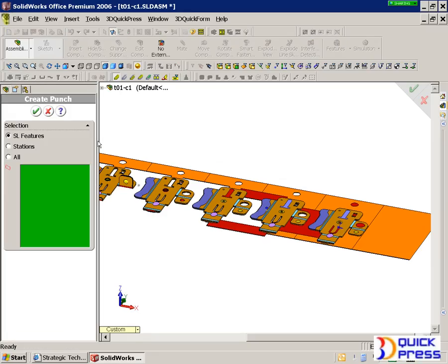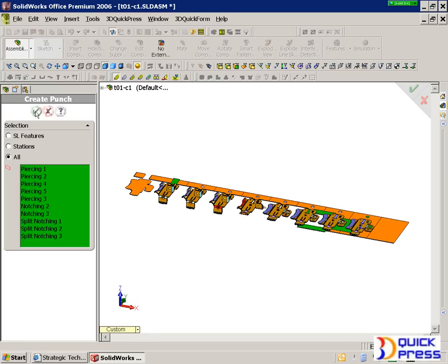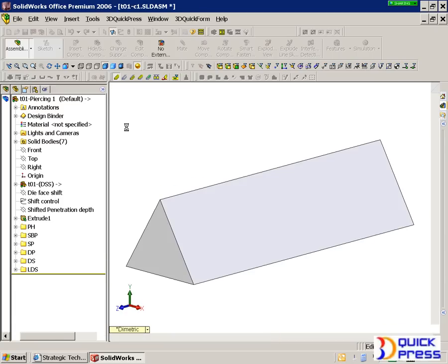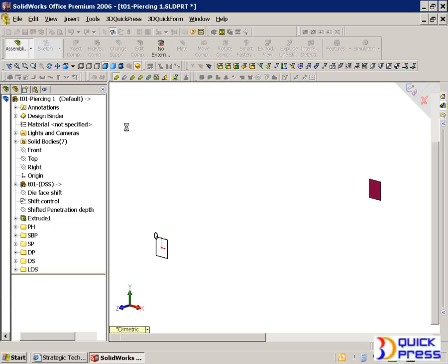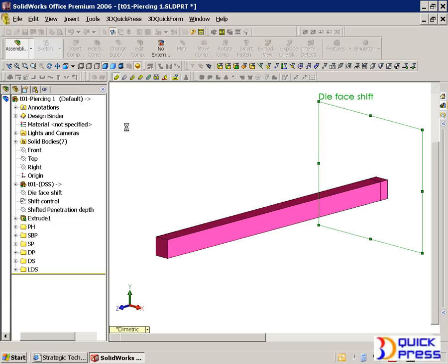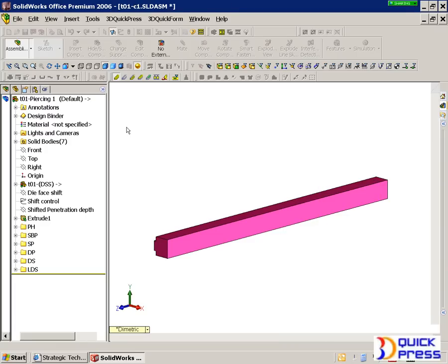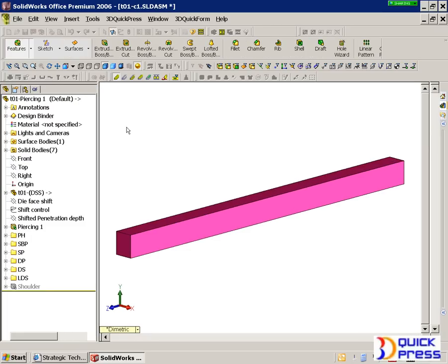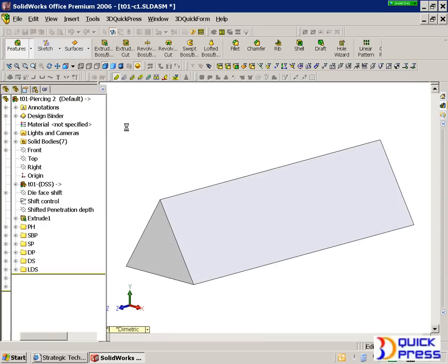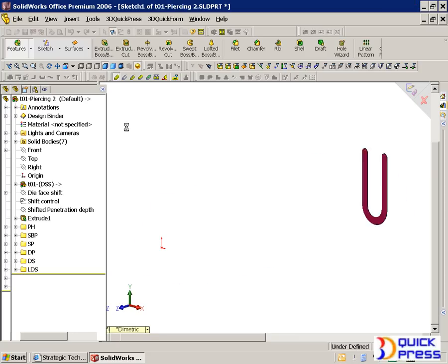Now, let's batch process the whole thing. Let's take it and create all the cutting punches in real time. What this will first look for is similar punches. Let's say you have a similar piercing diameter, which is a purchase punch. It's going to first look for that in the catalog. If it can find a straight shank, it will. If it can't, it will create a stepped one. Now, it will create all the holes through the entire die set based upon the current job information. It will also create any drawings necessary for each punch.